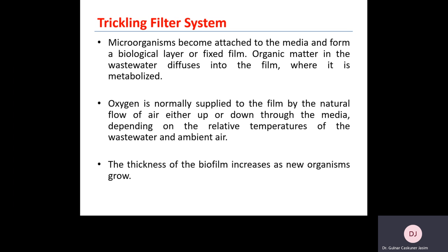Trickling filter system. In this trickling filter system, attached microorganisms are used. Microorganisms attach to the media and form a biological layer. Organic matter in the wastewater diffuses in the film, and is metabolized in that film. Oxygen is normally supplied to the film by the natural flow of air, either up or down through the media, depending on the relative temperatures of the wastewater and ambient air. Thickness of biofilm will increase with time as new microorganisms grow.